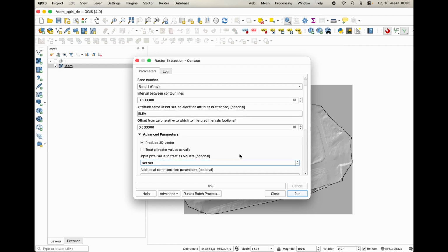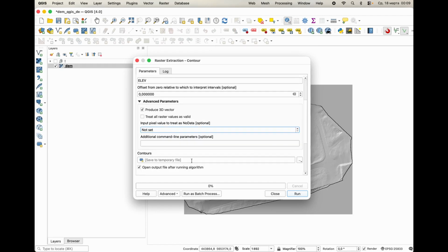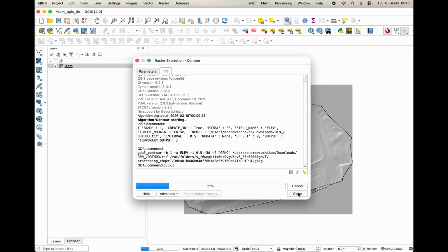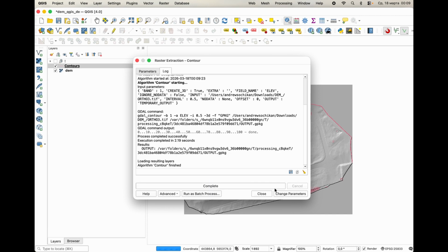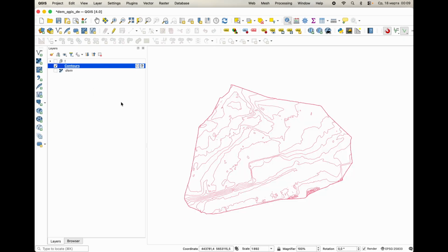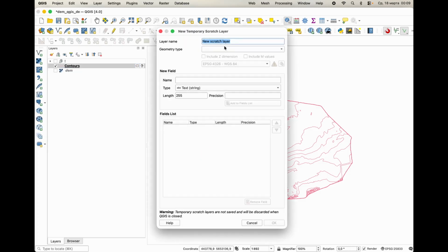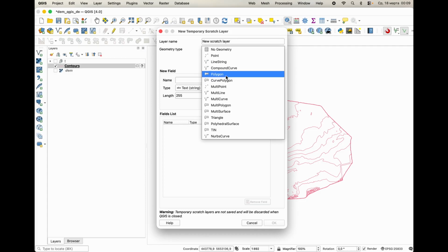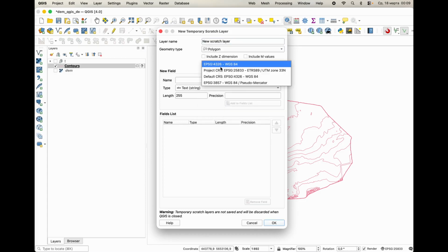So the first step here in QGIS is to load the generated raster and use it as the basis for contour creation. We take the elevation model derived from the laser scan and transform it into line work. In other words, we convert the .tif file into contours. This is the point where the surface begins to turn into a classical terrain representation. Once the contour generation is complete, we can close that step and review the result.